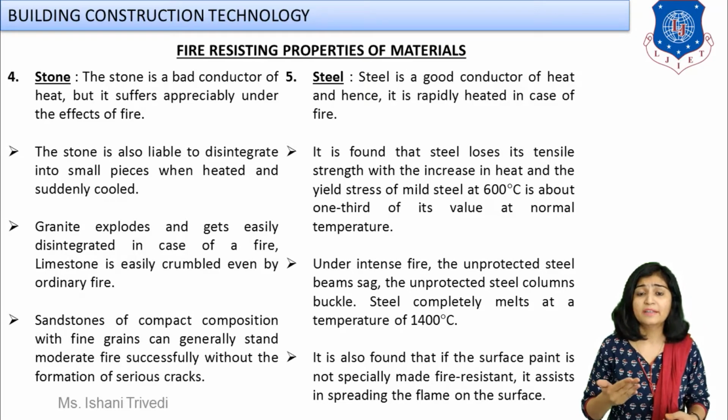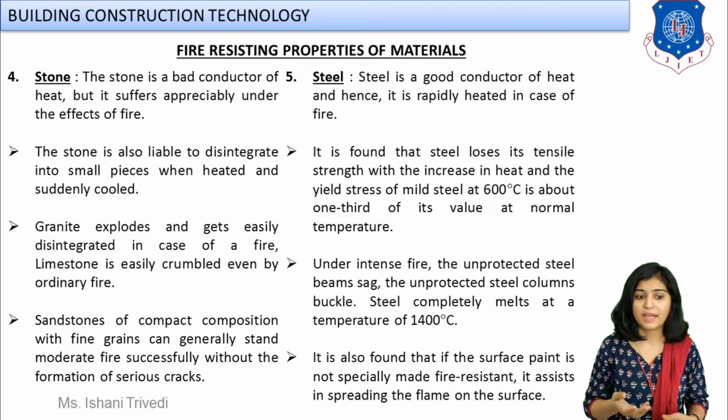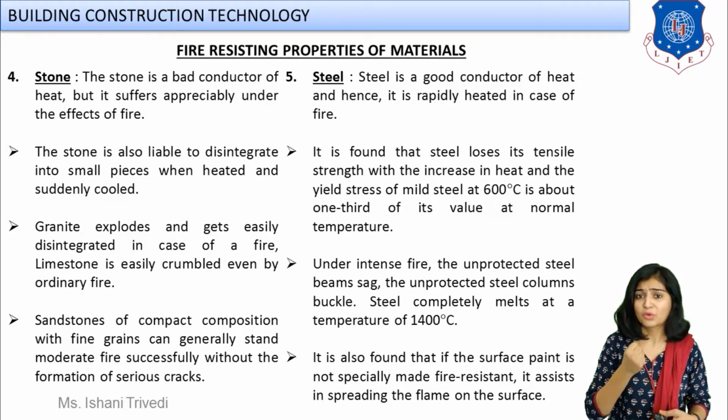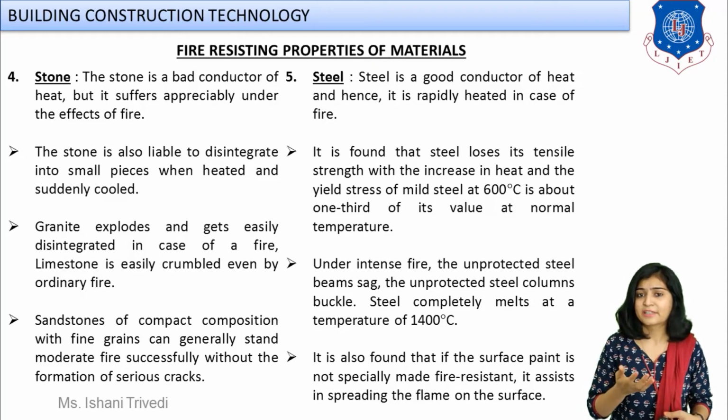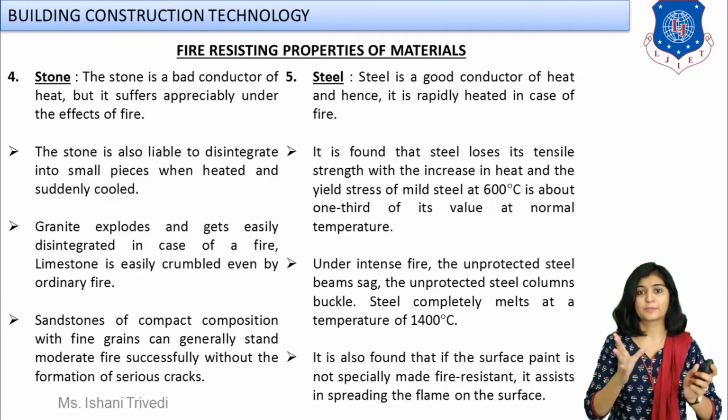We have certain different categories like granite. As I told you, granite explodes and gets easily disintegrated under the effect of fire. Limestone is also easily crumbled, which means it is easily broken. About sandstones also, as I said, stone is a kind of material that, if you give it heat, if you give it fire, it is going to take heat and expand, and if you splash water on it, it will explode.